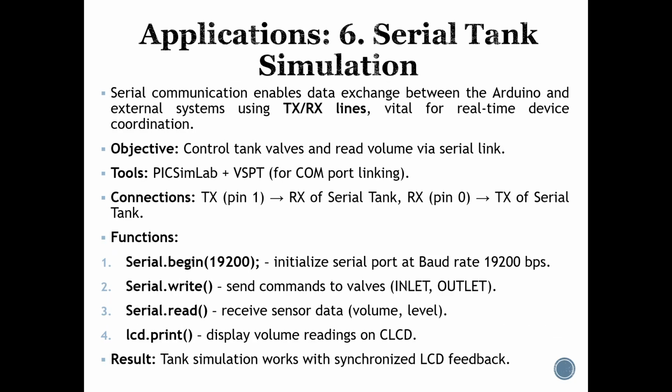Then I worked on serial tank simulation. Here the Arduino communicates with the virtual tank software via serial communication. I controlled actuators like the inlet and outlet valves, heater, and cooler using Serial.write commands. Sensor data such as volume and temperature were received using Serial.read. I also learned synchronization techniques using baud rate 19200 to ensure accurate data exchange.